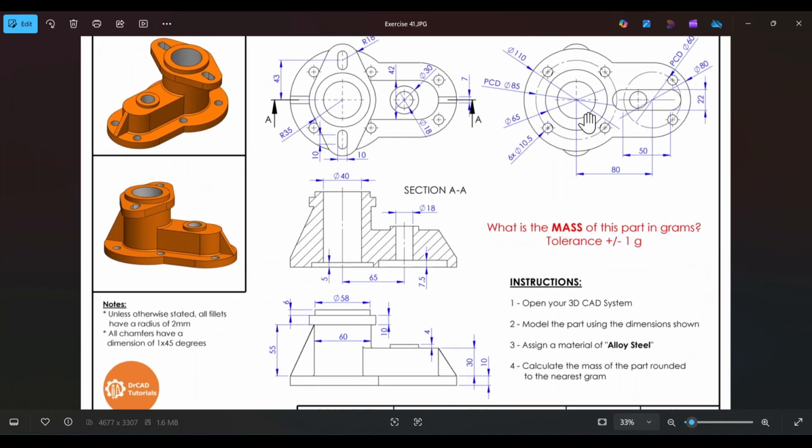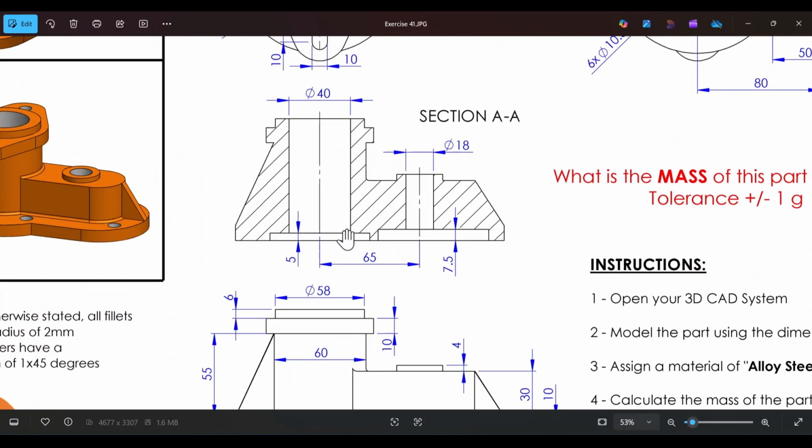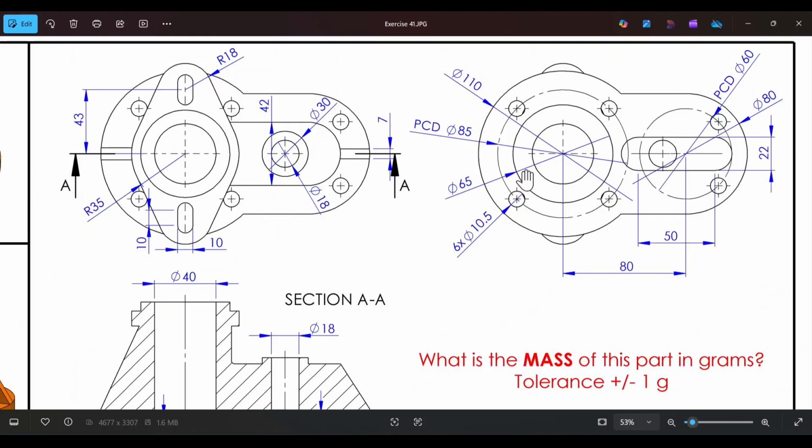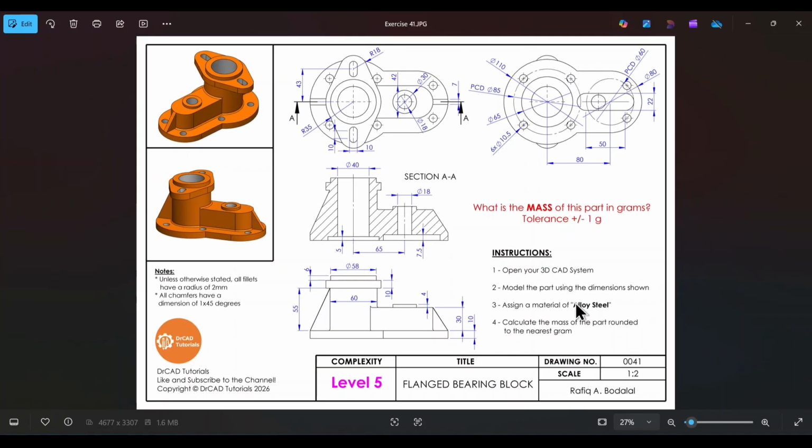And the reason why I've added the bottom view is because if you look closely here, we have a recess. We have a pocket located on the bottom surface of the component. So we have a circular pocket, okay, circular recess, and we have a slot-shaped recess. Of course, all dimensions are provided in order to create these features within SolidWorks.